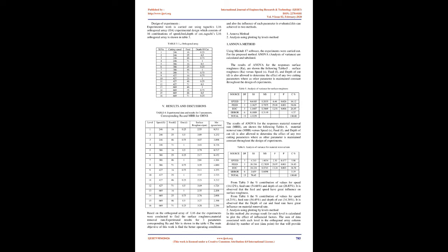Chandrasekharan et al. studied the machinability of AISI 410 on CNC milling for SR using the Taguchi method. The effect and optimization of machining parameters on SR is investigated. An L27 orthogonal array and analysis of variance, ANOVA, are used in this investigation. The experiment was conducted on a FANUC CNC milling machine. Work material of 32 mm diameter and length 60 mm was used.